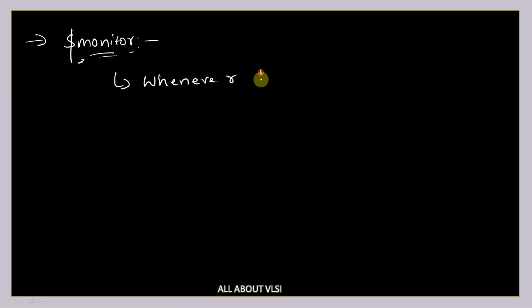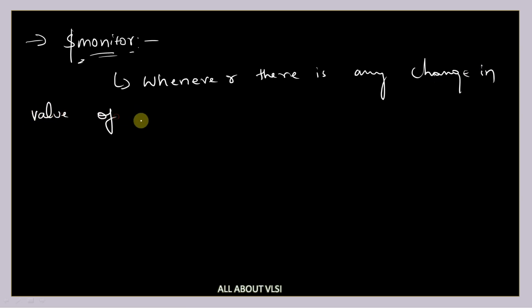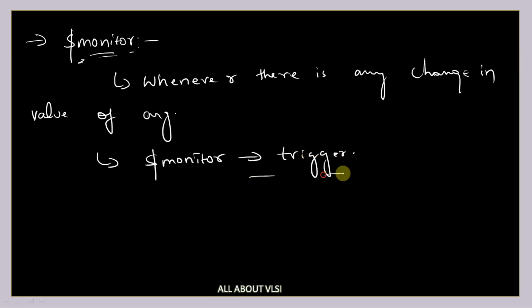Whereas coming to this $monitor, it is going to execute whenever there is any change in its arguments. I will write down here: whenever there is any change in the value of the argument, then this $monitor system task is triggered, that is, it is going to get executed.